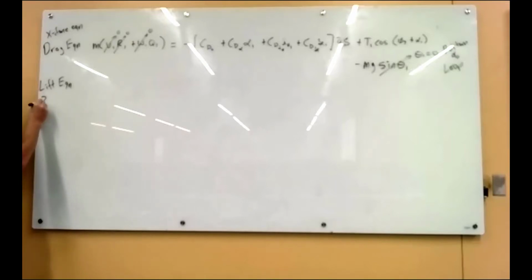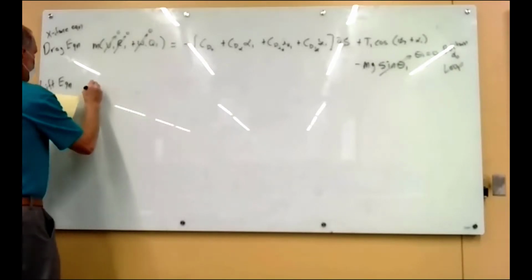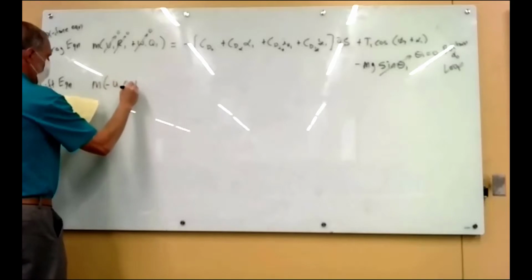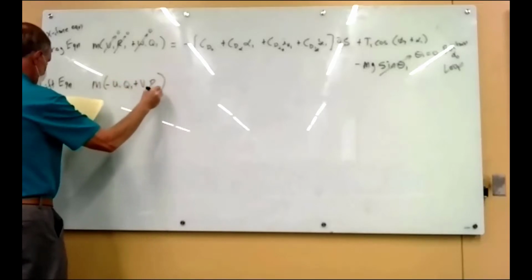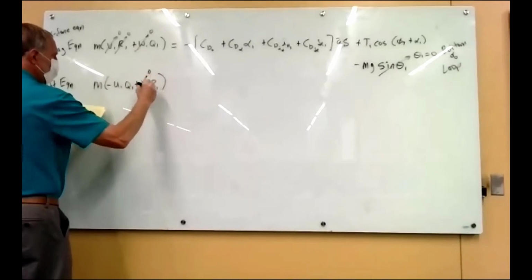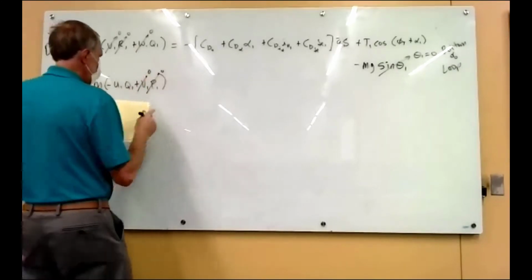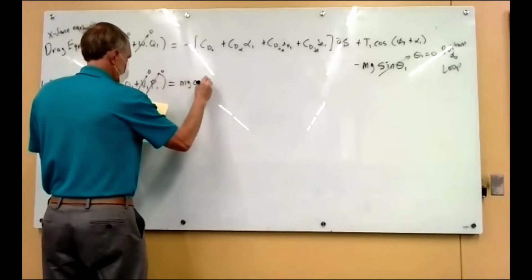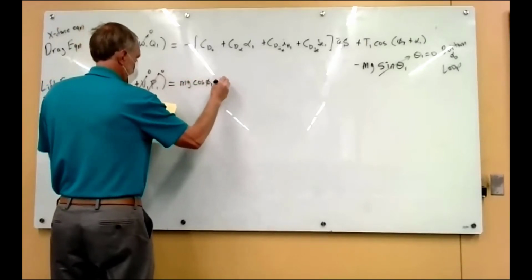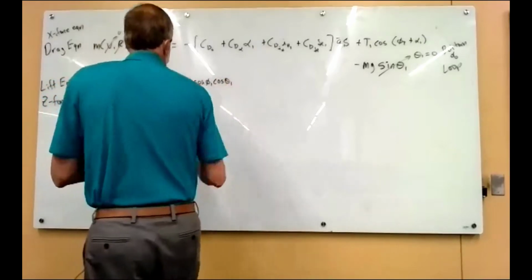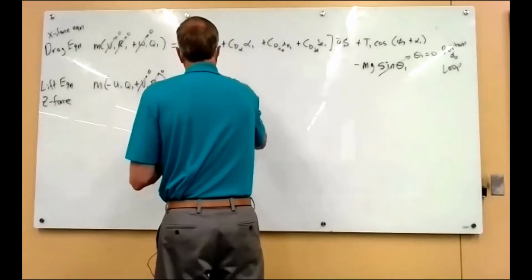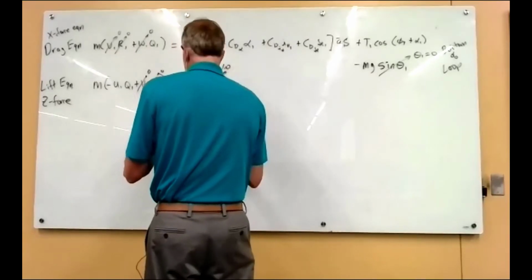And this is the Z force equation. Knock out those terms. There's the gravity term. The bank angle we said was 0, and the pitch angle is 0, so that simplifies.